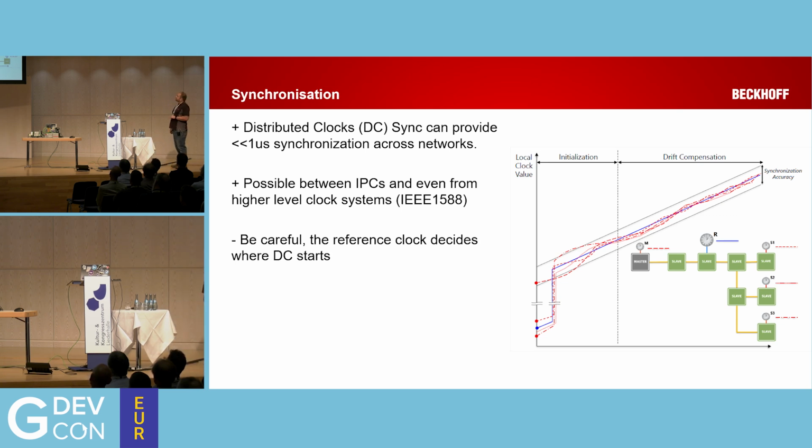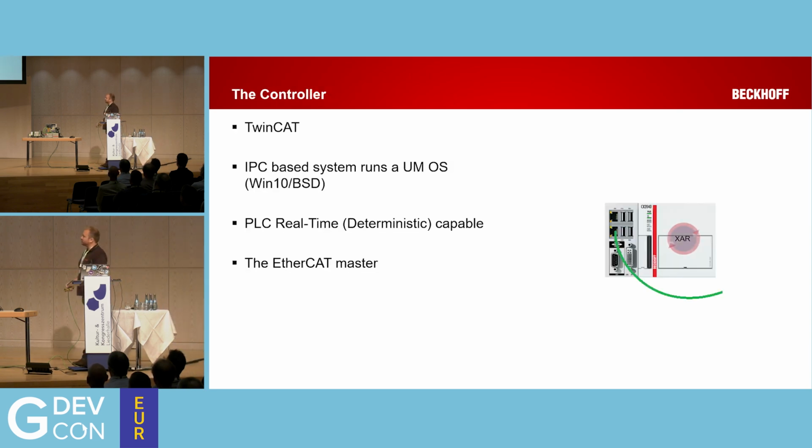Cool. So that all sounds wonderful. We have an EtherCAT system. It may surprise you to notice, given that I work for Beckhoff, the controller we chose for this project was a TwinCAT Beckhoff PLC. This gives us a real-time PLC, also with an OS that sits atop that, so Windows 10 in this particular case, but BSD, and there will be a Linux operating system coming in the future, which makes it a big open platform now for us.